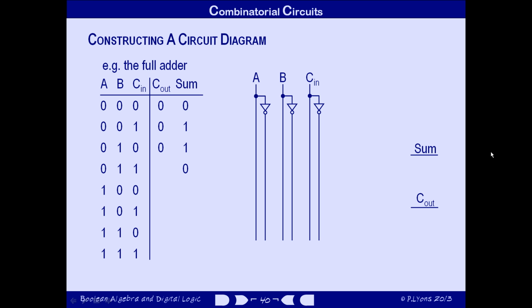But remember that this is a bit slice architecture. It handles one bit of each input and produces a single bit of the output. It's just the same when you're adding up a whole lot of multi-digit decimal numbers. You write the numbers down one above another so that the digits of the same significance are in the same column, and then you deal with one column at a time. If the column you're dealing with contains 2 5s, for example, then the digit in the output column is a 0. Of course, there's a carry digit that goes into the next column. But if we think of the word sum as a technical term that means an output digit with the same significance as the input digit in a particular column, then it makes sense to say that the sum is 0.